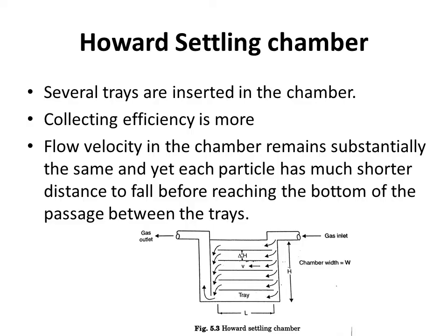The collecting efficiency is more for this method. The flow velocity in the chamber remains substantially the same, and yet each particle has to travel a shorter distance to fall before reaching the bottom of the passage between the trays.